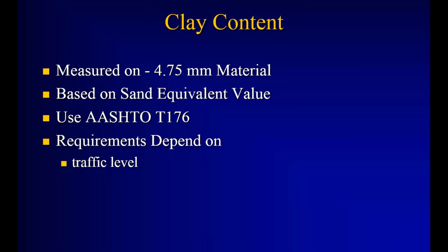Basically, in the sand equivalent or clay content test, what we do is we introduce our sample into a stock solution. That stock solution is actually calcium chloride in solution. And what it does is the clay actually floats up in that solution because it's this thin saucer-shaped material. It kind of floats or suspends, I guess is a better term, in that stock solution. The sand deposits at the bottom of this graduated cylinder.